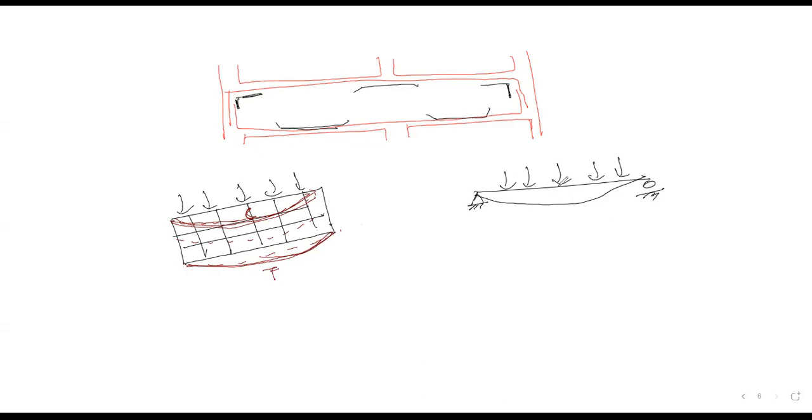Tension. Yes, sir. Okay, so on a simply supported beam, there is compression and tension. Now, remember compression and tension like this: whenever a negative sign is there or a positive sign is there, negative is treated as compression and positive is treated as tension, yes or no? And all of you know that concrete is weak in tension, yes or no?